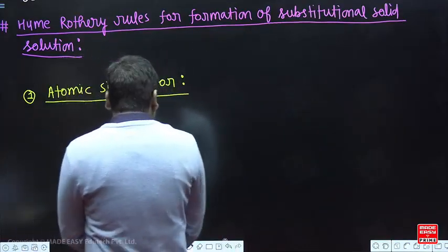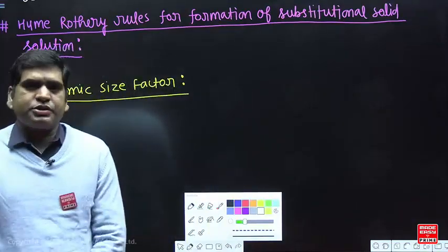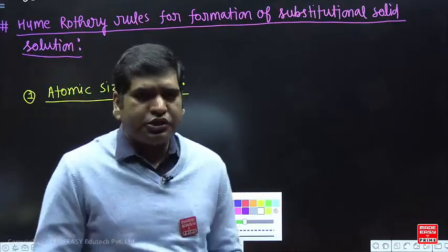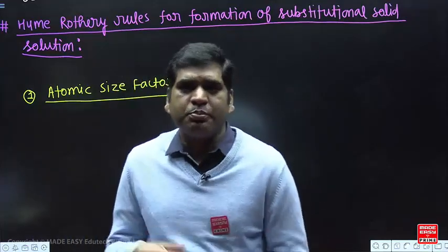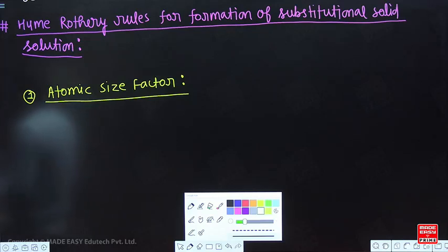Atomic size factor. The size of both of the elements should be almost same. There should not be difference in more than 15%. Then only this kind of solution can be formed.